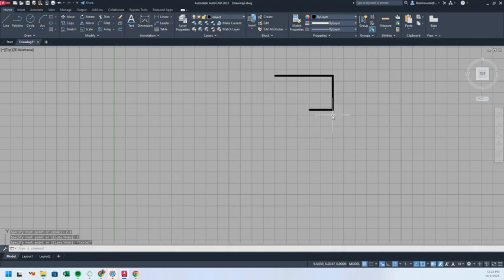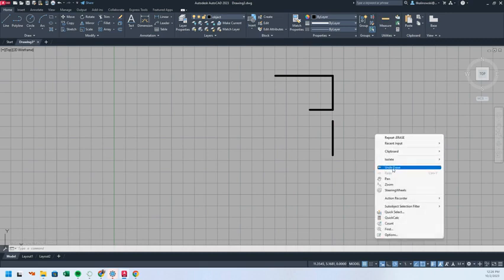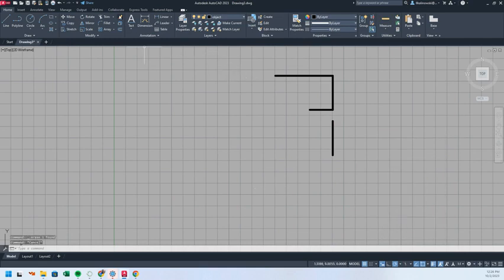Now, before I said I'm going to create a placeholder that comes down 1/2 inch. So I'm not going to erase that line. I'm not going to do anything with it. I'm just building off of it. I'm going to continue to draw a straight line down. This one is 1.5. And I could continue drawing, but I think I'm going to stop there and just try to mirror it. And I want to go in and find that little placeholder just by selecting it, and then I'll erase it out. Now I hit delete on my keyboard, but you could also go to erase. You could also come up here to erase on that as well.